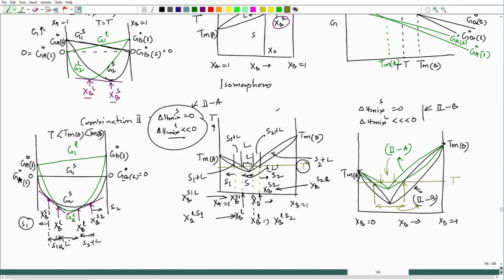And that actually leads to a condition called deep eutectic, shallow eutectic. Because of these differences, in one case the liquid stability goes up; in the other case liquid stability is still there farther below the melting points of both the metals, but that stability would be a little less than case 2B. Okay. So, I just wanted to reflect that.